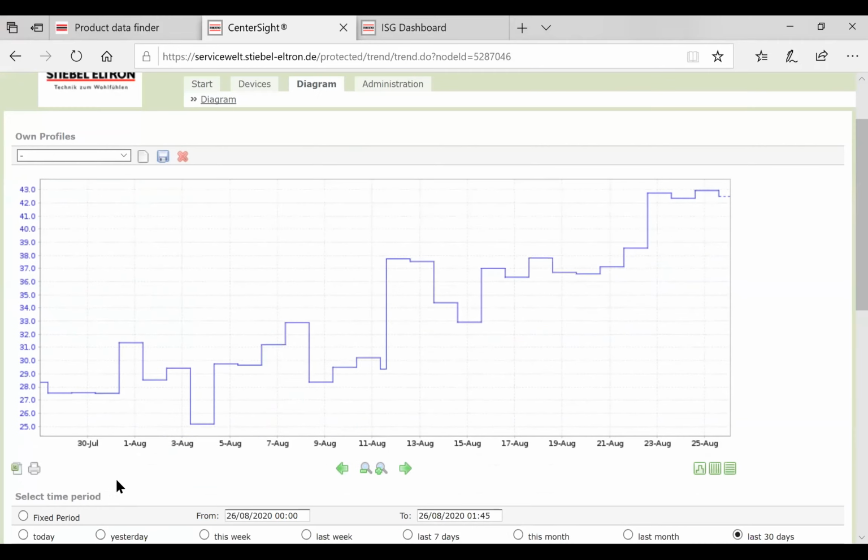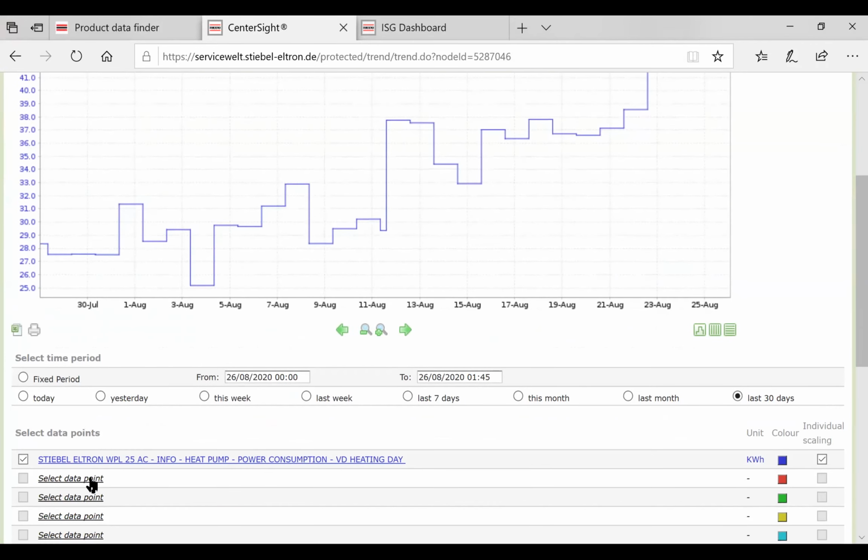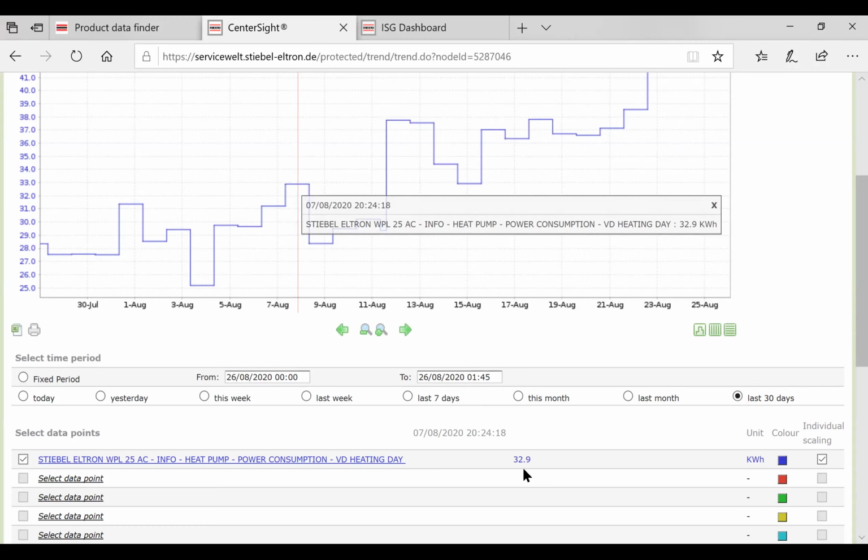But on that, we can overlay the heat output over the power consumption. And then, for every single day, we can look at what the consumption was versus what the heat output was. And then we can overlay, if we want, the ambient temperature. So we can look at the COP basically from that calculation. We can calculate the COP for any particular day, the average COP for any particular day, and see what the ambient sensor was doing at that time.